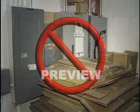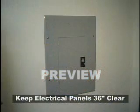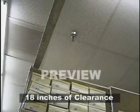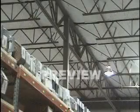Not only is it a bad safe work practice, but it's also a serious safety violation to block any emergency exits or electrical panels. In fact, fire codes require that they have 36 inches of clearance. The same applies to automatic fire sprinklers. They must have at least 18 inches of clearance to function properly in the event of a fire. It's not just good housekeeping, it's the law.